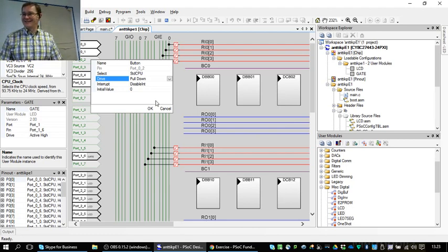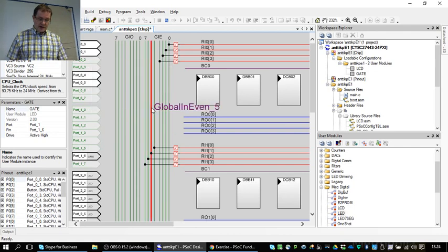Okay? Any objections? Initial value means that when the system started, after start, what is the state of that port? And initial value of 0, it's good. Okay. For pull down. If you put it pull up, then you would probably have initial value of 1. There. Okay.